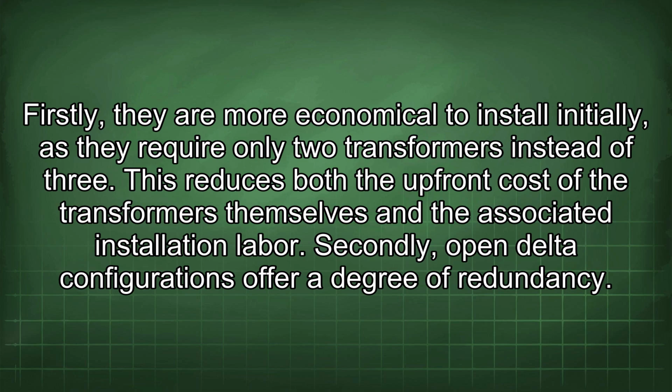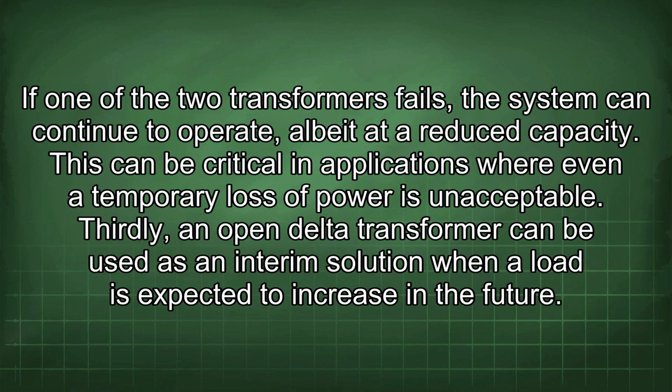Secondly, open delta configurations offer a degree of redundancy. If one of the two transformers fails, the system can continue to operate, albeit at a reduced capacity. This can be critical in applications where even a temporary loss of power is unacceptable.